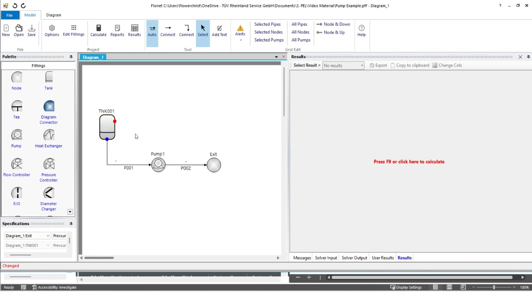Now, just to explain a little bit what's going on with that fitting, that's actually two nodes bolted together in the background. The reason why we did that is you might want, around pumps, to have a recirc line back in there if you want to ensure minimum flow. Previously you'd have two nodes to do that. It made more sense and was more intuitive to have a single node, so you can make sure you've got consistency with the pressures and temperatures, whatever it might be, within that node. So that's why that looks like that and makes it a little bit easier for the users.